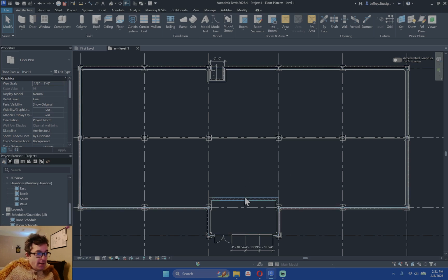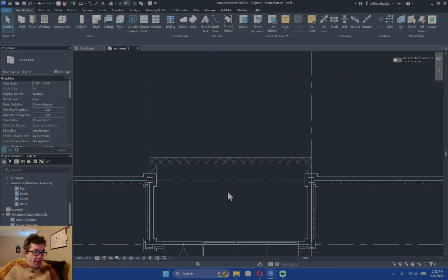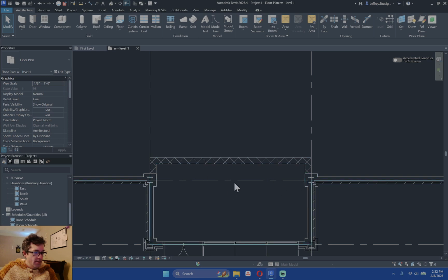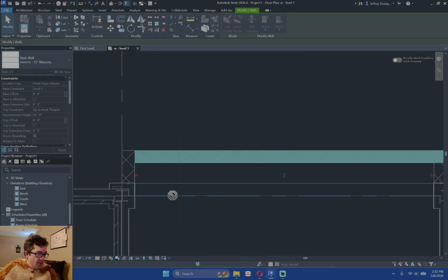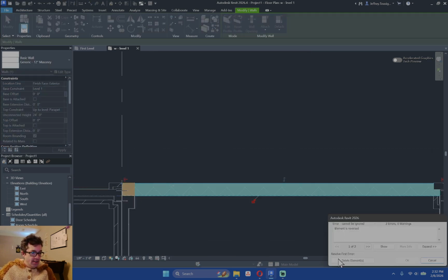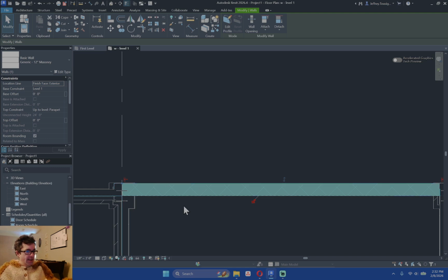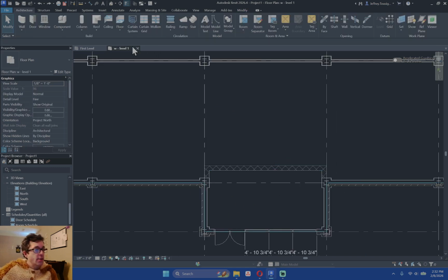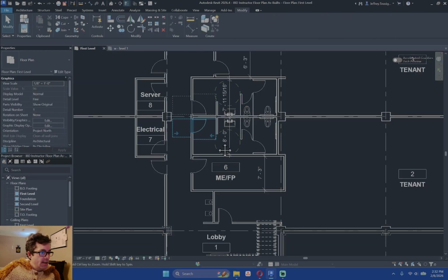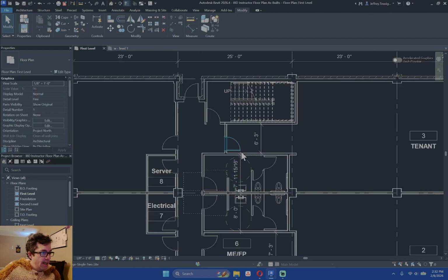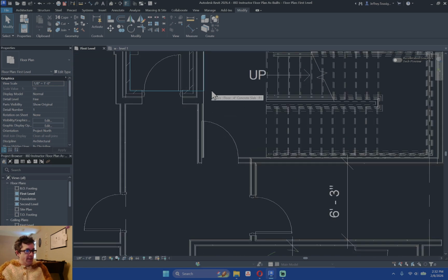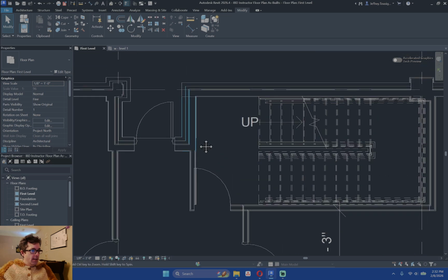And if we find out that we can go flush, then again, we have gained the space back. It's an easy fix. We can either delete these 3 walls and redraw it, or probably even just pull this wall down and realign it, tell it to delete those extensions, and then fix that. But for now, we're going to assume we're actually going to need a little extra space. And is that happening on the other side? The other side, the wall enclosing the stair is flush with its interior on the jog.